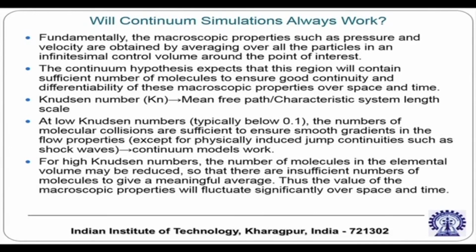Typically for Knudsen numbers below 0.1 you can use the continuum modeling safely, maybe you may have to adjust the boundary condition with a slip based paradigm instead of a no slip based paradigm, but still you can use the continuum considerations with adjustment of boundary conditions.